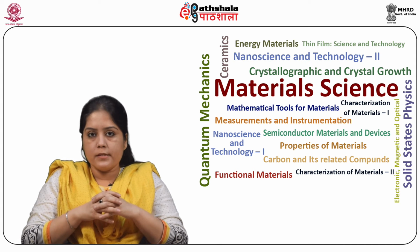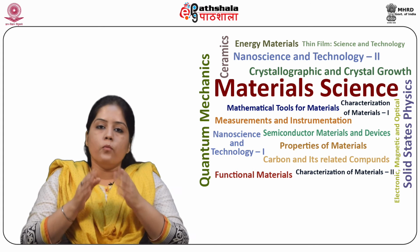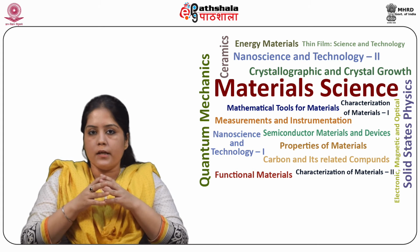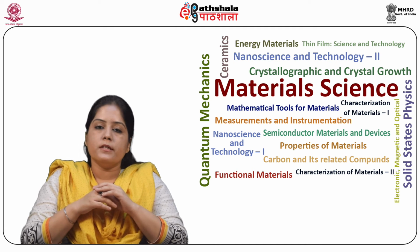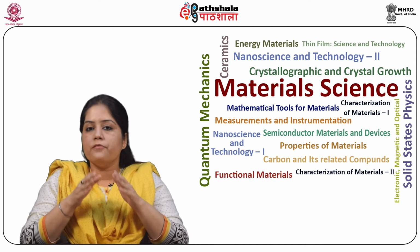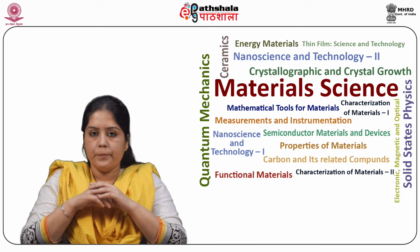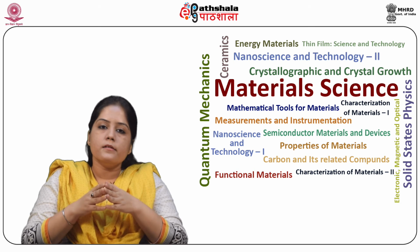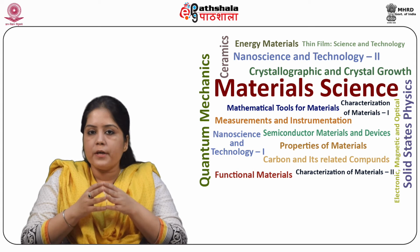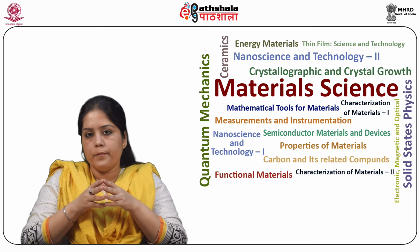Elastic properties according to the Voigt model. When there is a continuity in strain, the model can be treated as a set of springs in a parallel arrangement. It can be easily seen that Ec is equal to Fm Em plus Fr Er.